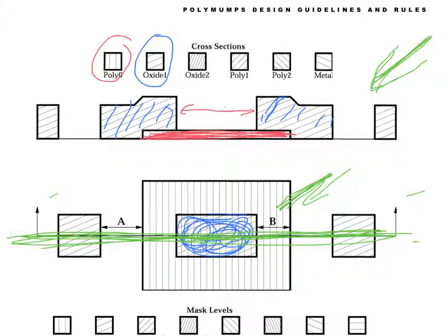And then we made a hole here and a hole here through the oxide. But we can't make this hole or this hole closer to the poly 0. So this distance here, from here to here, has to be B, right? That's what you see here. This is B, this is B. Actually, this is B. And this is A. Okay?